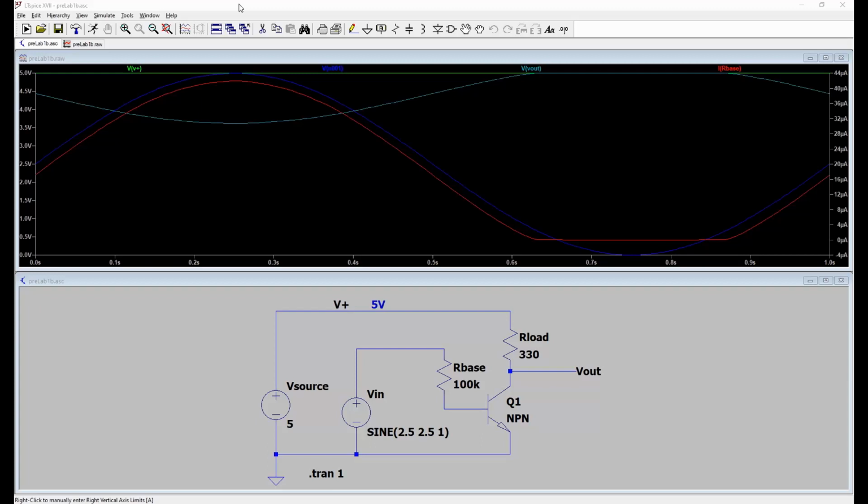Now, as a final note, in the lab, the professor is requesting a 1N4001 diode or equivalent be used in your rectifier circuits. So when you're creating the circuit, let's just modify this useless circuit with some more useless parts. Let's say we wanted a rectifier diode placed at the base of the transistor so that it never gets a reverse voltage.